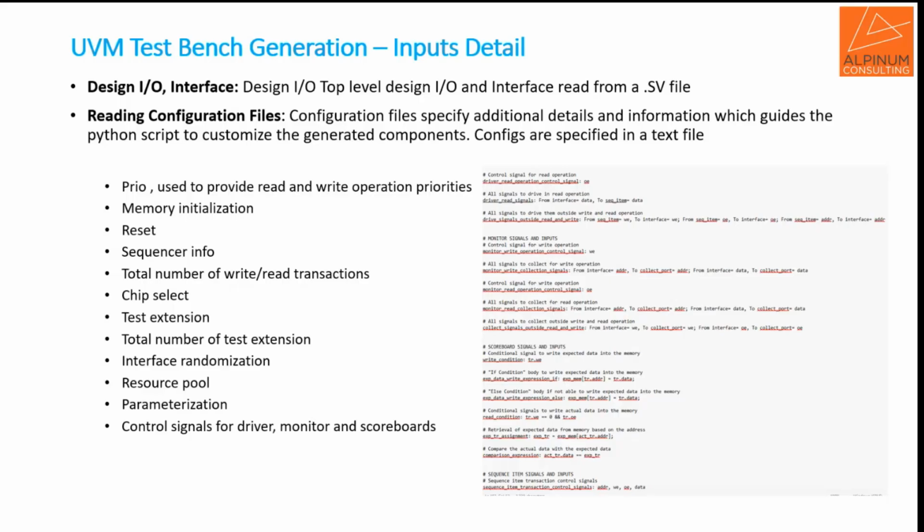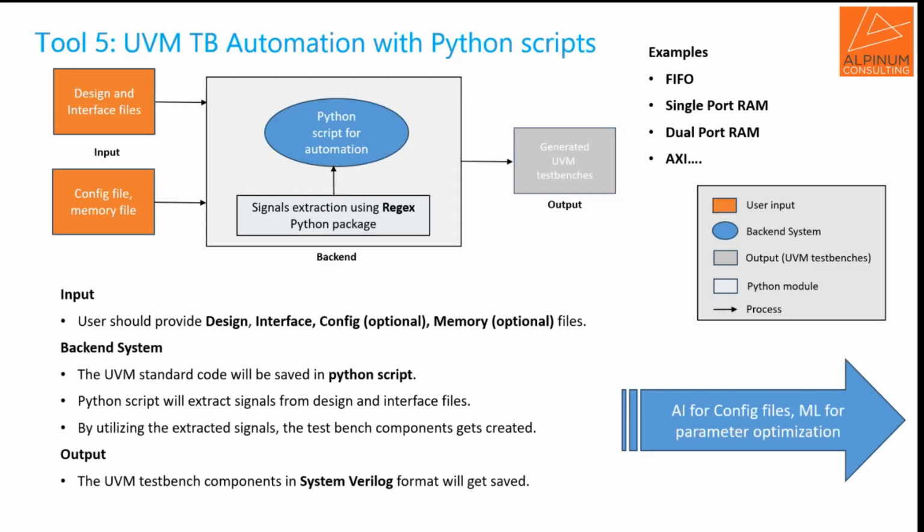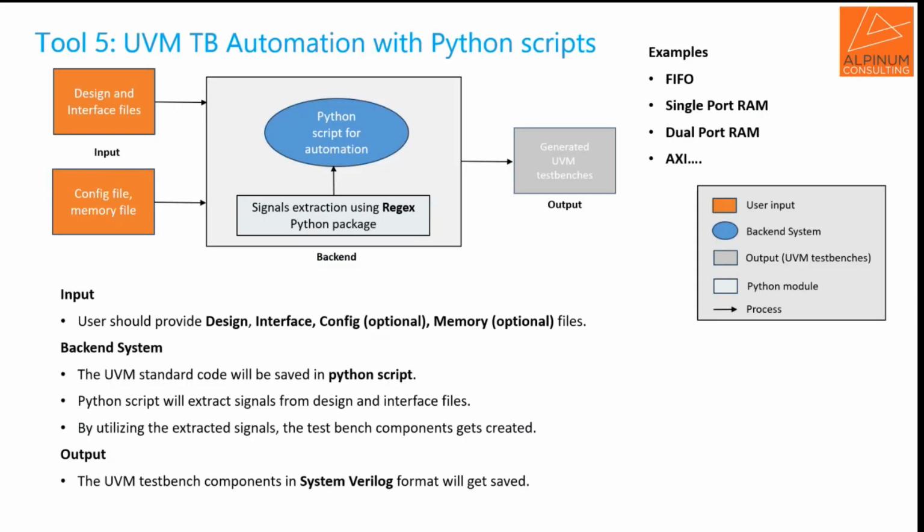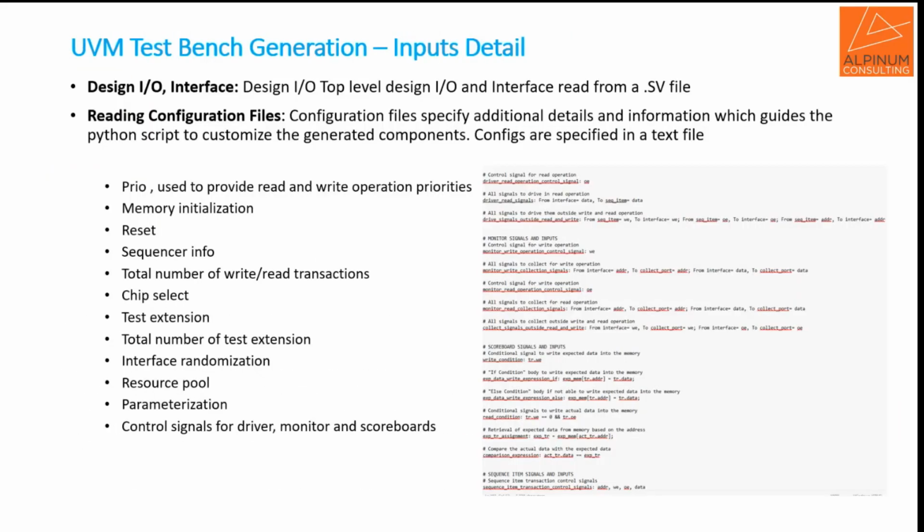Now these configuration files, as we have shown in the previous slides and also in the slide with the coverage flow integrated model, are going to take the inputs based on the coverage feedback flow and the results, and apply these different machine learning techniques to guide the stimulus: how we are going to generate, how we are going to direct, and how we are going to select the most effective tests from a large suite of tests to quickly close our coverage for a particular design.